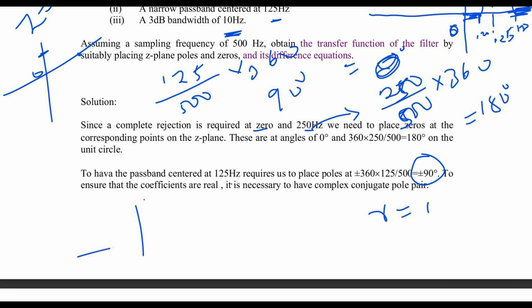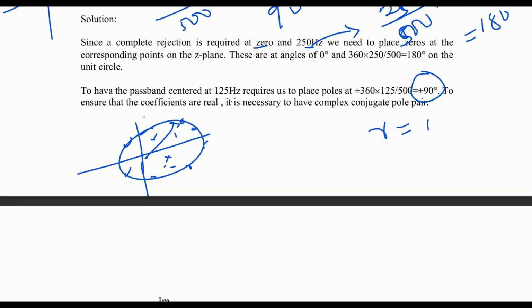So when you draw the unit circle, the radius here is 1, and the zeros will lie on the unit circle, right? The poles ideally should lie inside the unit circle, so they are the ones which have hectic characteristics in terms of calculating their radii. So to calculate the radius of the poles, there is a formula. It's more or less an approximation, right?